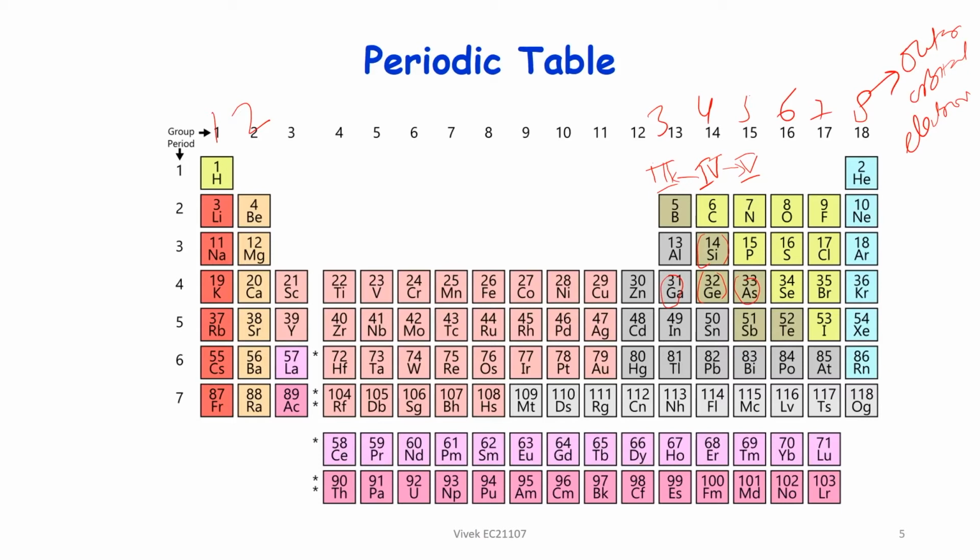So you have gallium here, arsenic here. This gallium arsenide will be one compound semiconductor. But remember, gallium itself is not a semiconductor, right? But gallium arsenide is a semiconductor, or aluminum arsenide, or aluminum antimonide, indium antimonide, indium arsenide. These are basically semiconductors. So you have group 3, group 5, they are called 3-5 semiconductors, and their average electrons in the valence band will be 3 plus 5 divided by 2, so that is 4.